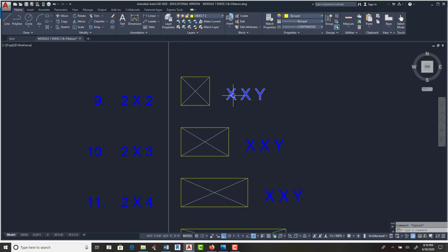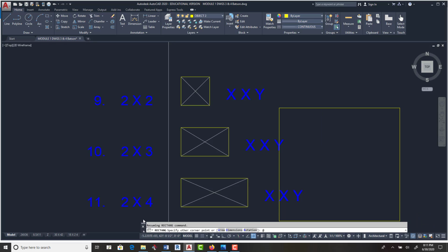There's a 2 by 2. Let's see, a 2 by 2 is, let's do another way. A rectangle. Left select. Now, since you clicked the rectangle, AutoCAD doesn't know where you are. So at this relative point, since it's not on the 0,0 origin, you've got to type in at that point. So at is that same at that they use in your email. So at, there it is, that little A, that little ampersand above the 2. Okay? So at XY coordinates 1.5 comma 1.5. Enter. There it is.